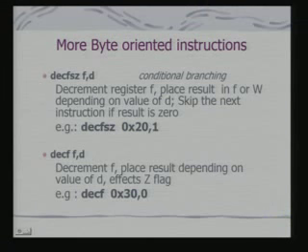The next instruction which has been fetched cannot be executed. So, that instruction has to be replaced by a NOP or no operation. So, effectively this instruction would now require 2 cycles for execution. That is, when the result is 0, this instruction will actually require 2 cycles for execution and not just 1 cycle for execution.